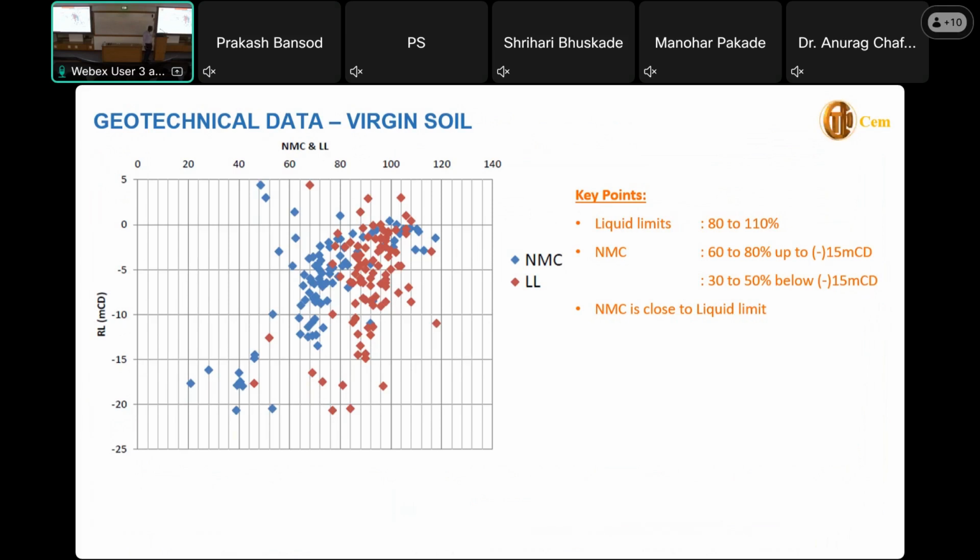Chart datum. Those not very familiar with marine work, they used to call it chart datum. Chart datum is a reference from which measurement is done from a port level. The port has decided a benchmark, which is 0, this chart datum. So all the levels and dimensions are measured from the chart datum. That's common in marine work. Otherwise, people just put RL or something in general.